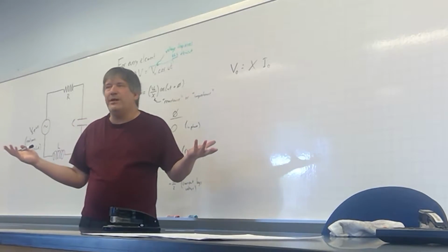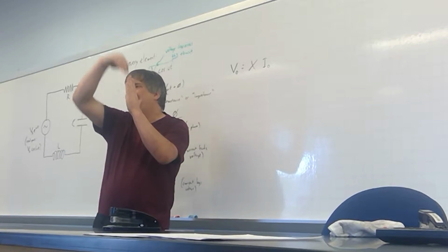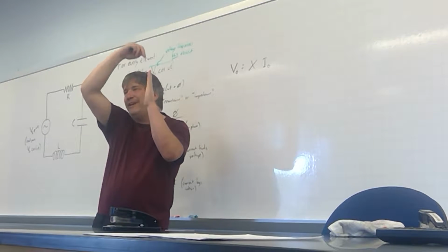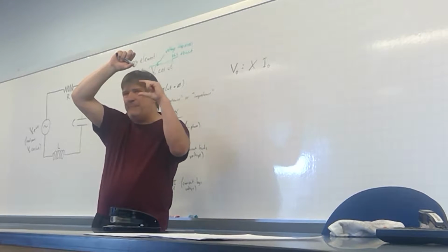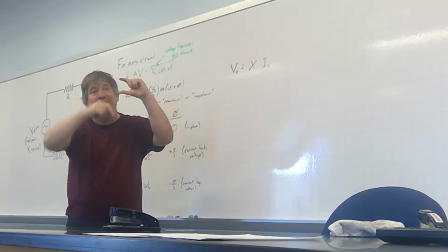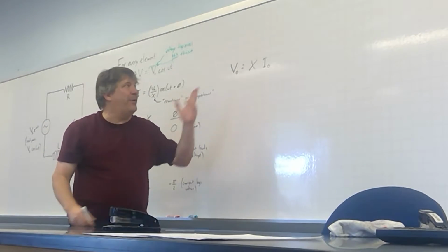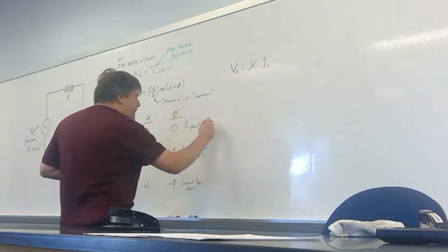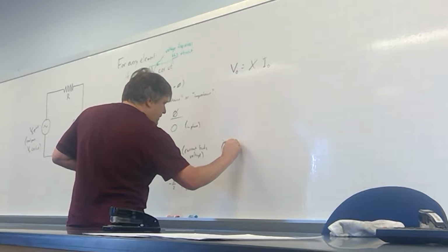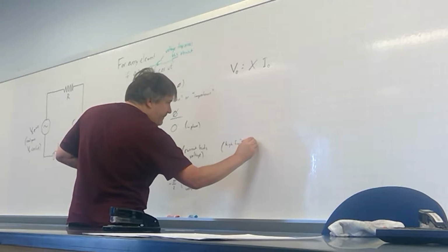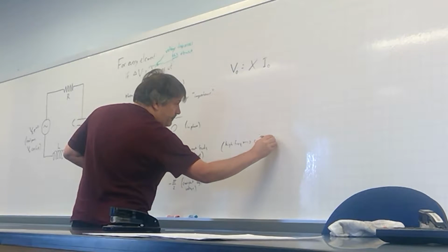Seems like a strange thing for a capacitor to act like, since the charge carriers cannot actually pass through it. But if I'm reversing the direction of that current rapidly enough, then essentially the voltage across the capacitor will stay pinned at 0 because I've given it no time to build up any voltage on either side of the thing. So at high enough frequencies, your capacitor acts like a short circuit, acts like a zero resistance wire.